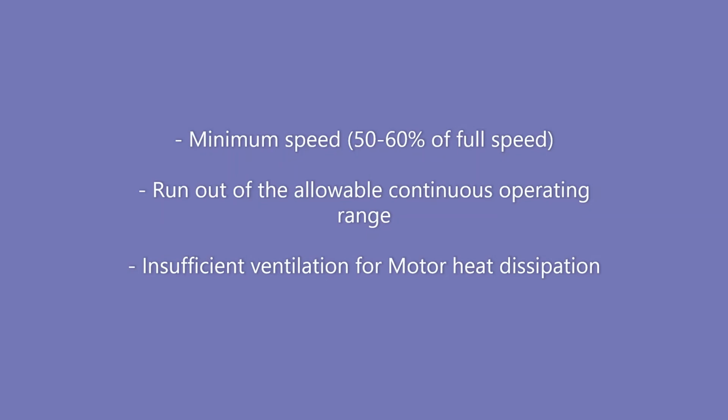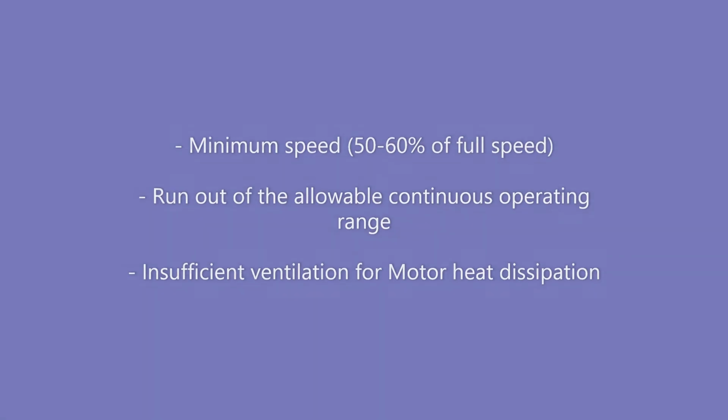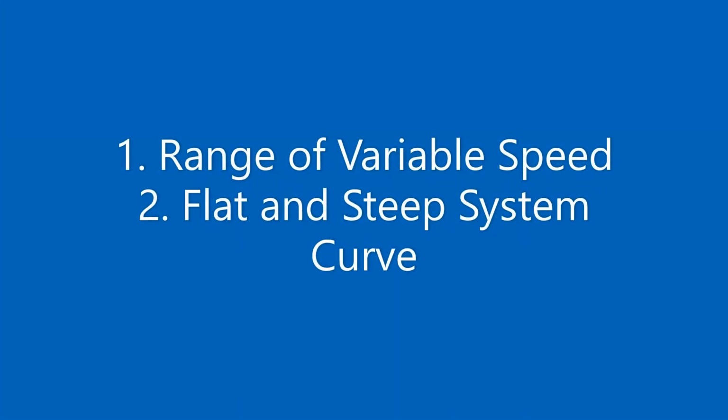Too low a speed for pump will damage the pump as it is running out of the allowable continuous operating range. In addition, the low-speed motor will cause insufficient ventilation for heat dissipation and cause the motor to trip due to overheating. 2. Flat and steep system curve.